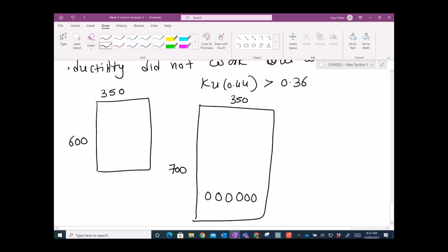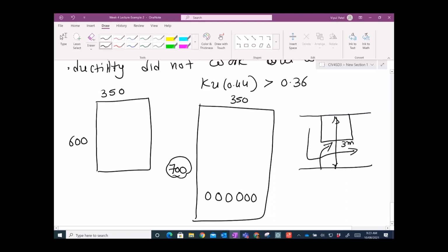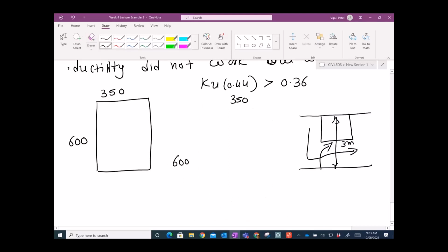Well, look, the architect will not like it if you keep increasing your depth, right? Because you can think of you have a house, floor to floor height is let's say 3 meters, and then someone said that my structure engineer wants this massive beam here, and then you need to bend down every time you go in your room. Well, you do not like it, right? So the architect said, let's keep it 600. Okay, you keep it 600. You keep all this depth at 600.